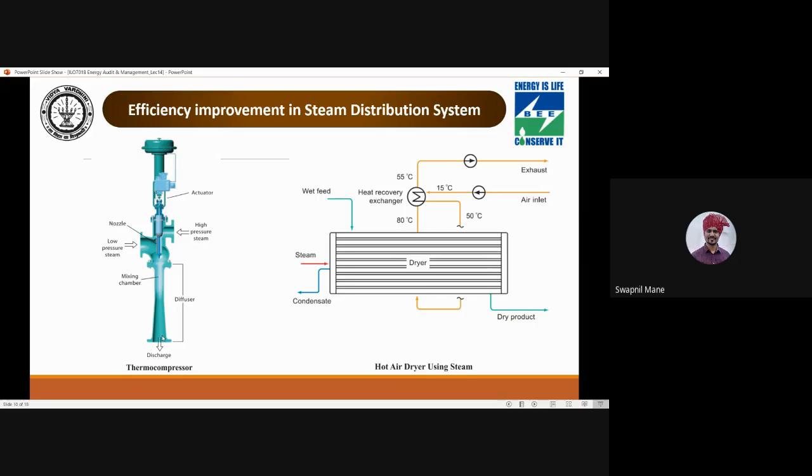So in most cases, the product material, the carrier gas, and the equipment also need to be hot so that the total energy required includes heat leaving the dryer in the exhaust flow. Okay, then this includes the latent heat of water being evaporated, but the sensible heat of the hot gas can be significant.